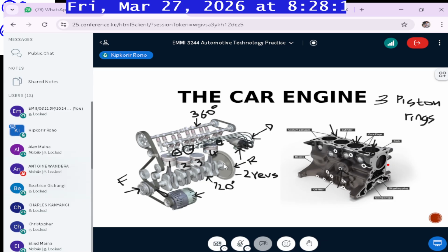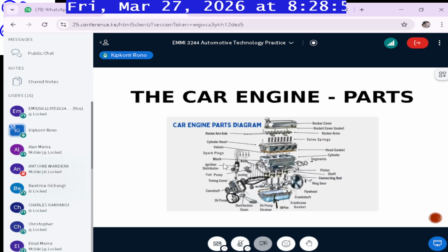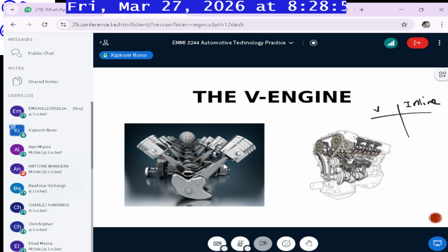So the heat developed is normally circulated within the engine using the oil. I said oil functions both as a coolant as well as a lubricant. So it will carry some of the heat and deposit it to the walls of the engine block. And then on the other side of the engine block, the coolant circulates and takes away the heat. So the coolant and the oil do not mix. All right, the coolant and the oil do not mix. They simply exchange heat across a wall, which is part of the engine block. So it behaves as a heat exchanger, if you know how heat exchangers work. Anyway, I just wanted to mention that fact.